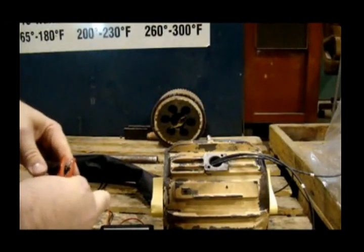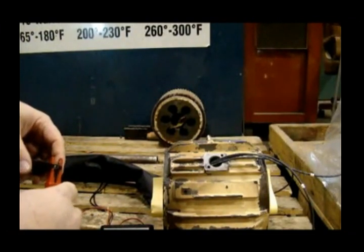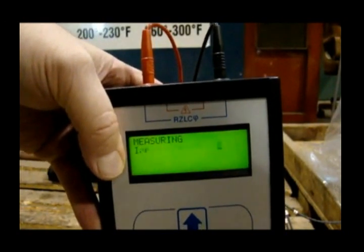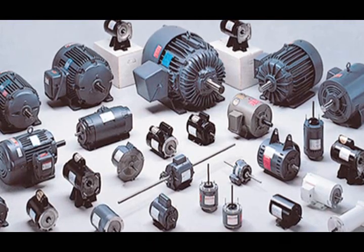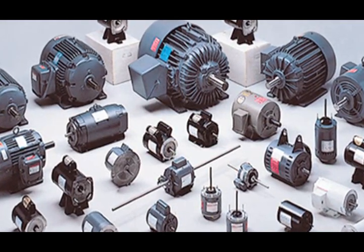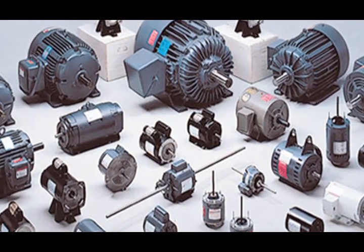Recommended tests include stator winding resistive imbalance testing, stator winding insulation resistance testing, polarization index testing, step voltage testing, and surge testing. Needless to say, there are many types of motor test equipment, including online and offline, single-phase and three-phase, portable and benchtop, plus rack-mount motor test equipment.